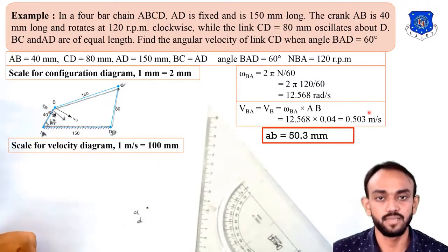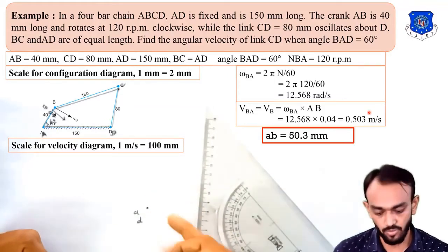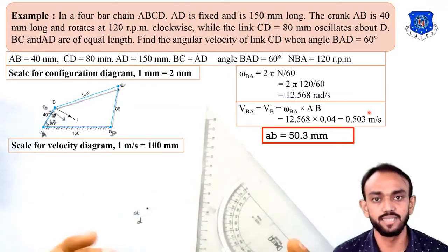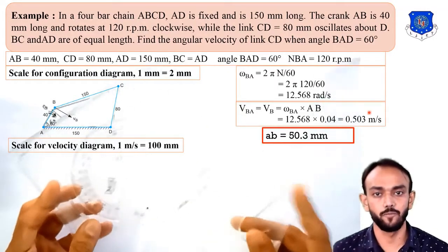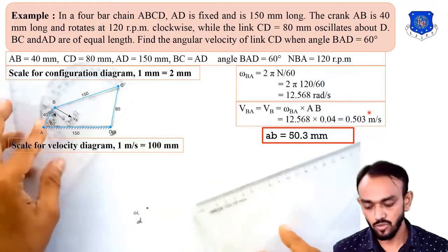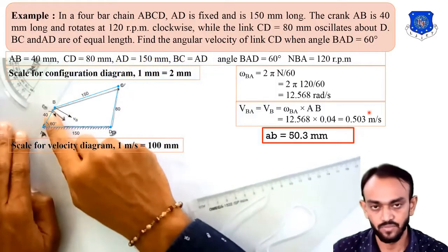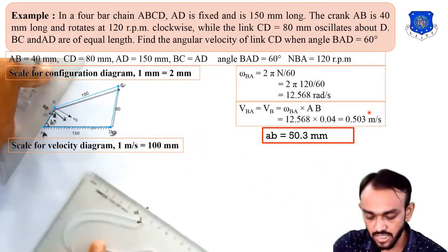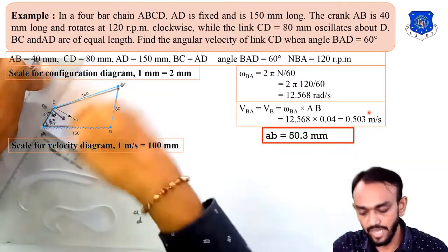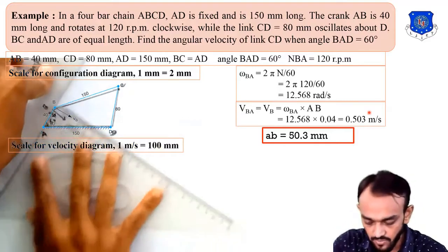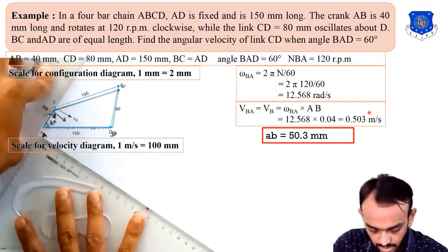There are multiple methods, and using these methods we can draw the perpendicular here from AB. The first, easiest method is using the set square. Using 2 set squares you can find the perpendicular at any link. So first of all, check this. First I set the set square here, parallel to the link, and then using the second set square I will attach it here. This is the perpendicular to this link. So I will set it here along the line which is passing through this. So check this, like this.